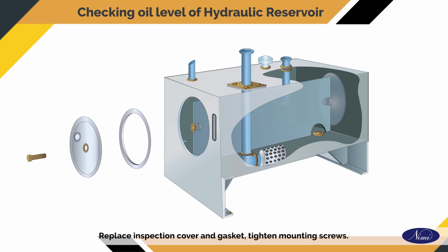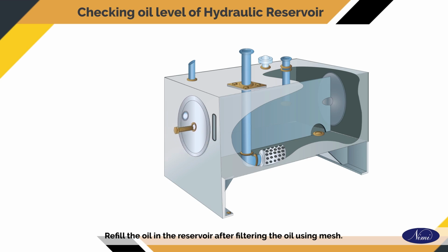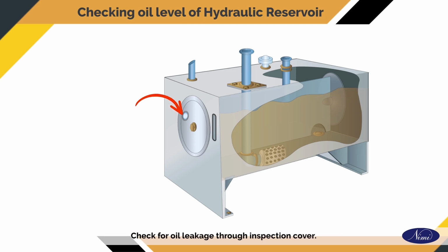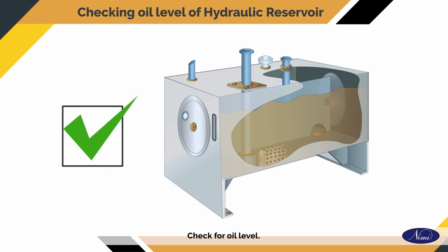Replace the inspection cover and gasket. Tighten the mounting screws. Refill the oil in the reservoir after filtering the oil using mesh. Check for oil leakage through the inspection cover. Confirm no leakage of oil. Check the oil level.